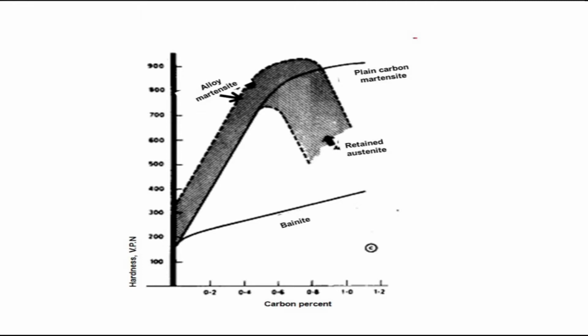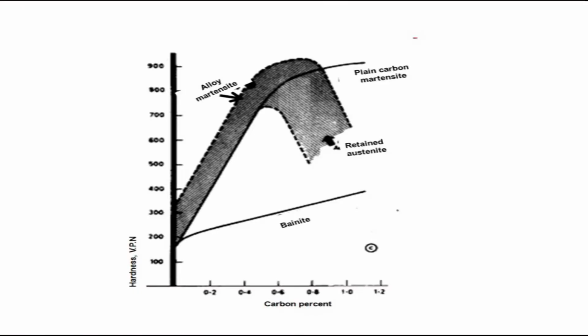See, martensite's nucleation, as I told you, they have given in the books also. Let me just read out the books. That particular portion is a very interesting part. A single plate of martensite in steel grows in 10 to the power -5 to 10 to the power -7 seconds, just like microseconds, to its full size at velocities approaching the speed of sound.